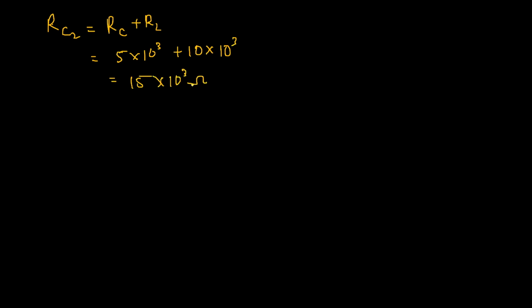So now for RC2, I know it's RC plus RL, which is 5 into 10 to the power 3 plus 10 into 10 to the power 3, which is 15 into 10 to the power 3 ohm.